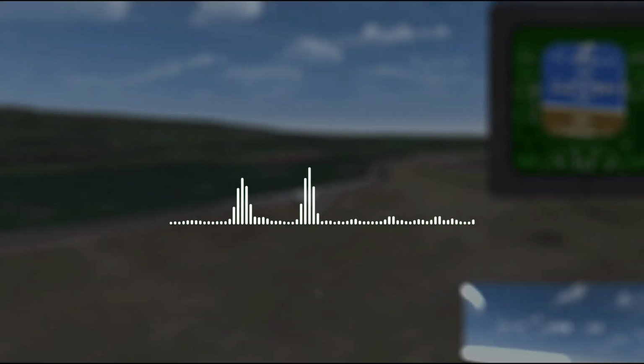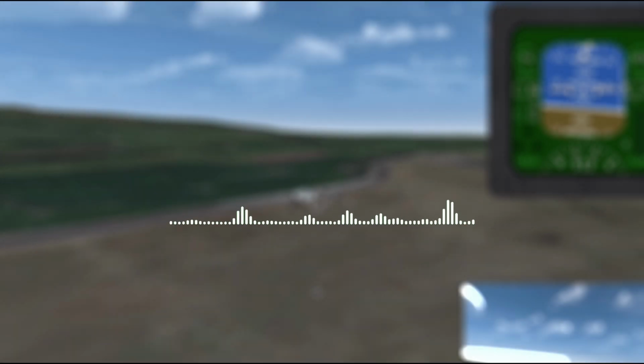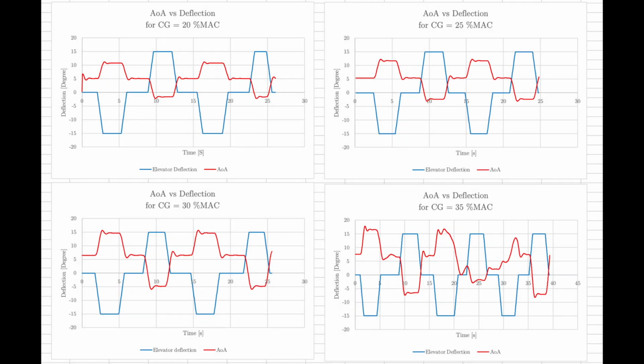Moreover, the aircraft does not respond with strong enough responses at forward CG values, i.e. in the negative Z-axis or a high static margin value, when the elevator was deflected. However, trimming is required for aft CG positions to counteract the maximum elevator deflection's sudden right rolling motion.